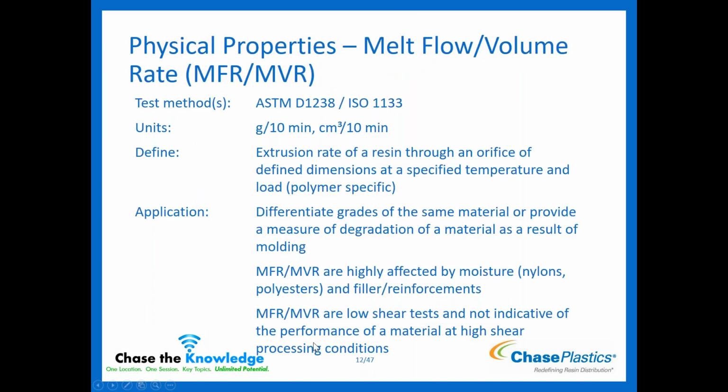So now let's move on. Physical properties for melt flow and melt volume rate. This essentially is the extrusion rate at which the resin is going to go through an orifice at defined dimensions at specific temperature and load.